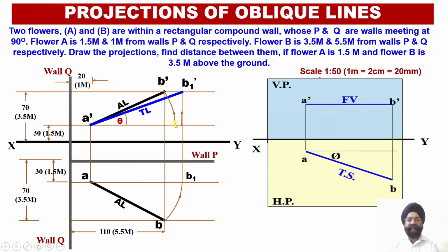So we are going to get the second point of intersection over here, and the name of this point of intersection of this curve and the horizontal locus line through this point A dash is B2 dash. Once we obtain this point B2 dash, it means that we have been able to obtain our apparent length elevation projection A dash B2 dash parallel to the horizontal plane. Now we are going to extend this vertical projector through this point B2 dash into the horizontal plane up to the locus line of the point B. So this is the horizontal locus line which is passing through the point B.